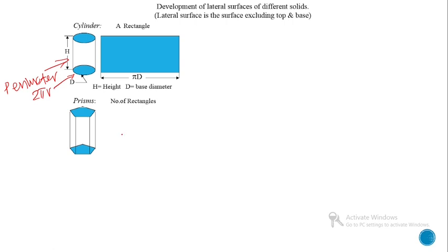In the development of the lateral surface, we must represent those vertical edges by thick straight lines. In the case of a cylinder, there are no particular vertical edges, so all the vertical lines are generators, and all the generators have the same priority, so we can't represent a particular generator. For construction purposes, we can draw generators using thin continuous lines.